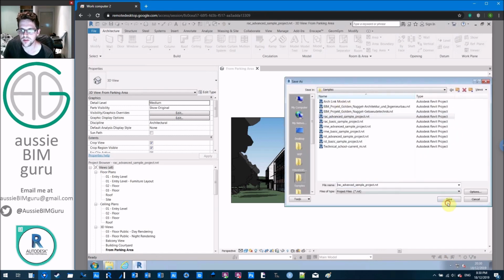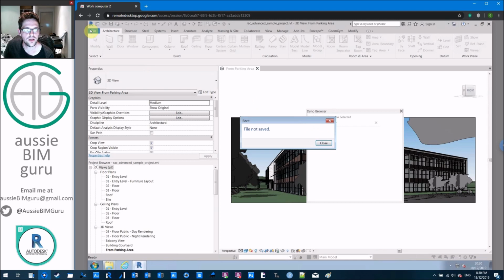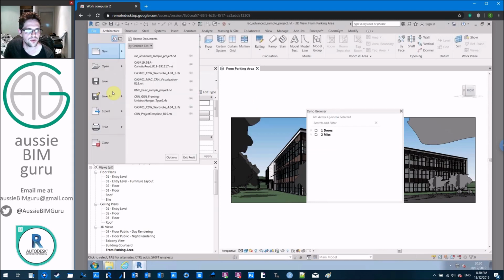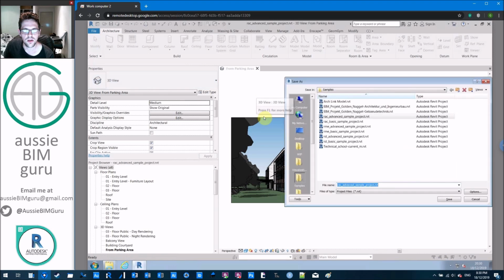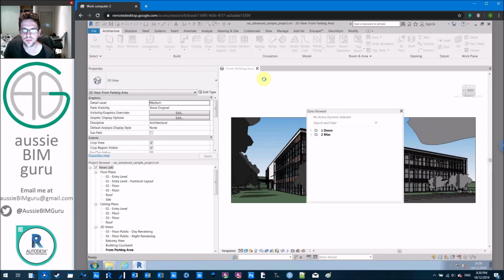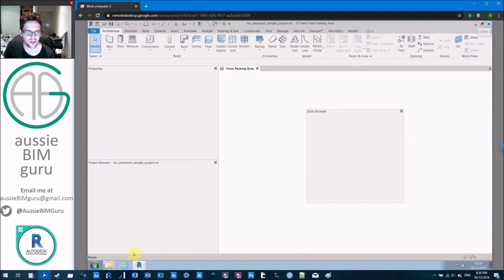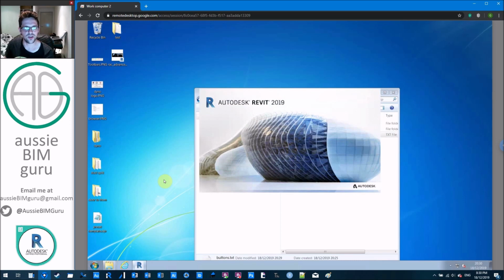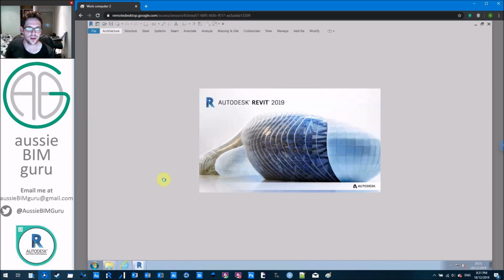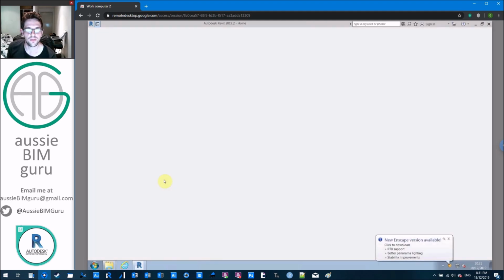So what I might do is just save, and then I'll try, okay, I'm in a read-only file. That could also have something to do with it. I'll save it to my desktop. And again, we're going to reboot Revit to see if it can remember what we're doing. Ideally, it should remember the paths that you tell it to remember between opening and closing Revit. It should store that data, and then it should boot up the ribbons once it remembers where they are. But it's all part of that boot up process. So fingers crossed, we'll see our ribbon show up once Revit gets started.